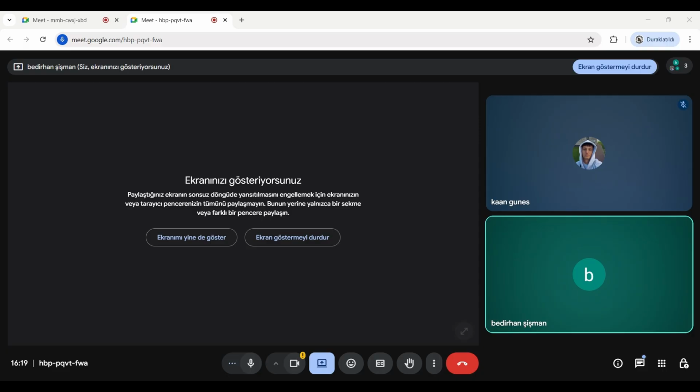Okay, I want to talk about what we learned in this lesson. Today, we compared two important types of internal combustion engines, two-stroke and four-stroke. We learned that both engines are designed to convert fuel into motion, but they do this in different ways. The two-stroke engine completes its cycle in two piston movements, but the four-stroke engine completes the same process in four separate stages: intake, compression, power, and exhaust.